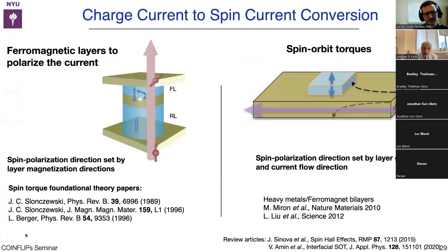So the positives on a very high level are that the readout signal can be larger. You can optimize the tunnel junction to have much larger magnetoresistance, whereas for the STT, the tunnel junction has to be a relatively low resistance area product junction, so you can't get the maximum possible MR. Usually the magnetoresistance increases with the thickness of the barrier because you get better spin filtering properties.